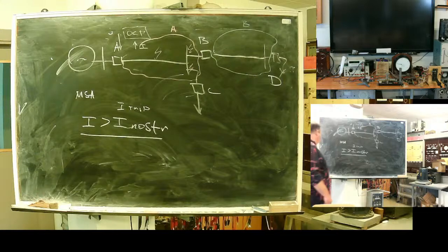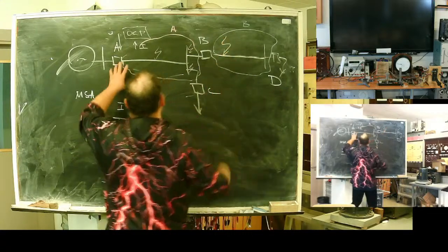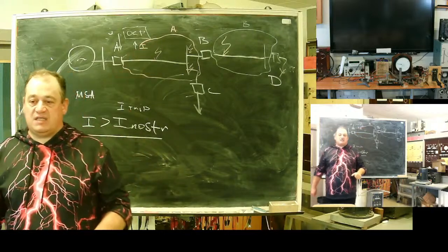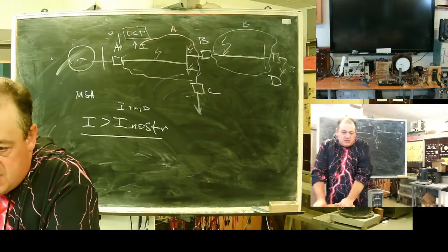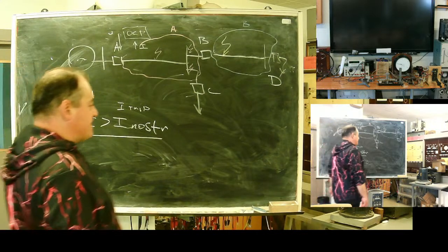But there is another question. Any fault within the red cloud, within the protected area, is internal. An internal fault is a fault inside the protected area. Sensitivity means the device should trip on any fault within the protected area. A fault outside of the protected area is external.